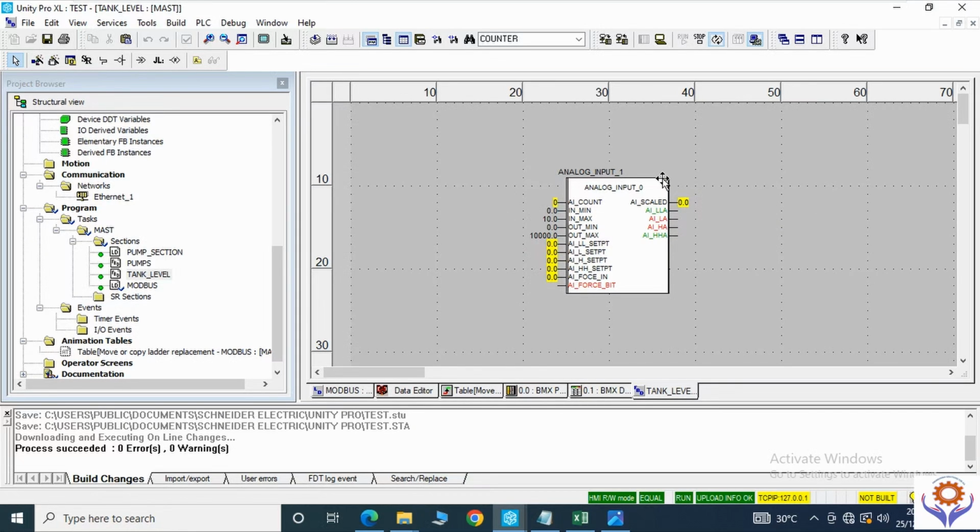So if you need to use integer, you have to scale everything in the SCADA. But if you take this direct scaled value, the real value, you can take this one in the SCADA without anything to be added in the SCADA systems. So if you add this one real, and if you put the maximum range, it will work automatically. Okay, and also you see here, you added the alarms, no? Low set points, and alarm. See, this is the alarm, and this is the set point. So you can add all the things the same.